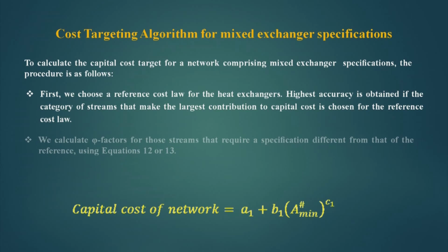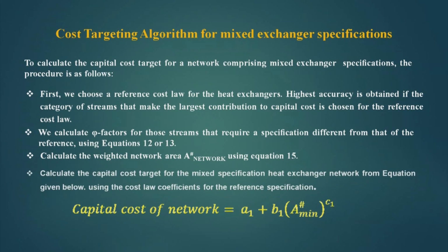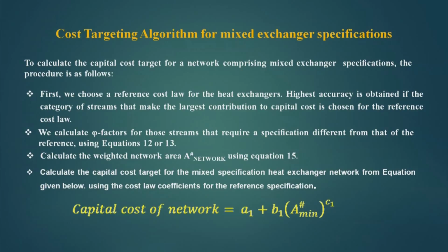Now, cost targeting algorithm for mixed exchanger specifications. Let us see this. To calculate the capital cost target for a network comprising mixed exchanger specifications, the procedure is as follows. First, we choose a reference cost law for the heat exchangers. Now, how to choose the reference cost law? There are some guidelines for this.